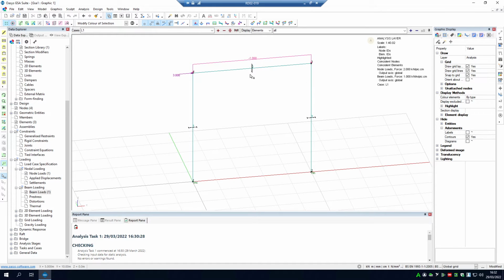This is something a lot of people make a mistake on. They will simply go like this and think just because it's in the middle, it'll take the entire thing. But no, you need the entire force, the entire beam, the entire node. If you want something annotated, you need to highlight the entire thing, right? So just keep that in mind. So now that we've annotated it, we know we're applying this load here and this load here.